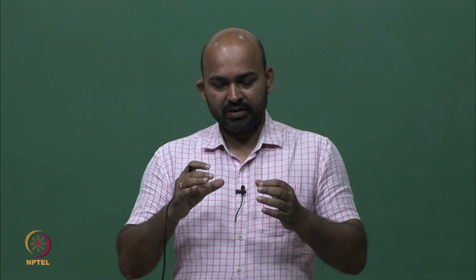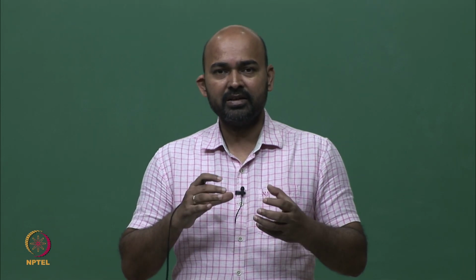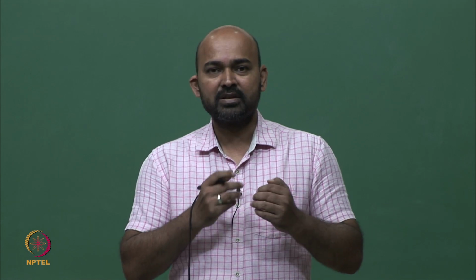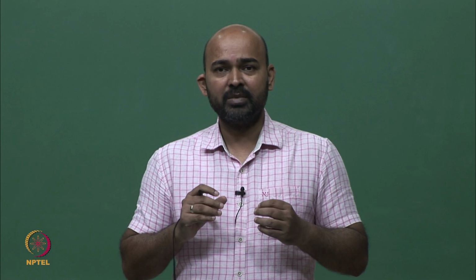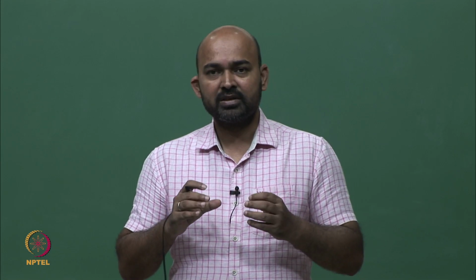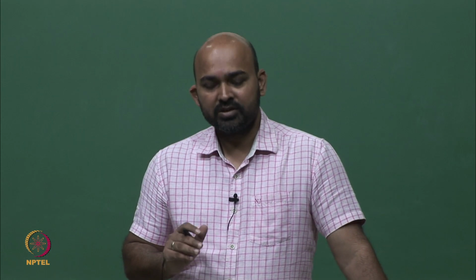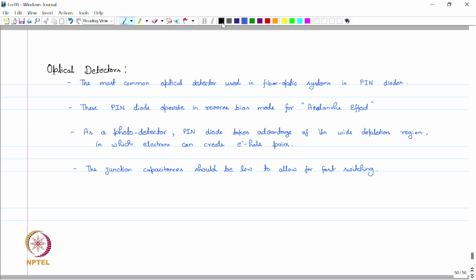So, we intelligently design these devices so that the junction capacitances or the stray capacitances between two different materials should be as low as possible. And the cross section structure of these PIN junctions is like this.